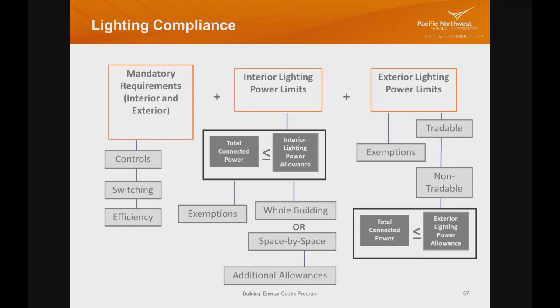Moving on, we'll speak now to the lighting compliance. Note you have qualitative type requirements that can't be measured in the software, like control requirements, switching requirements, efficiency requirements. You have to meet those through demonstration in your plans and installation. Otherwise, you're really trying to specify your proposed connected power such that it's less than the allowed power for interior lighting and exterior lighting.